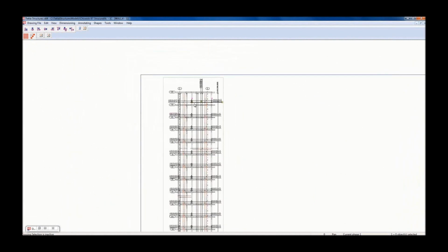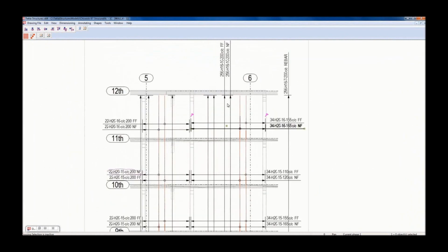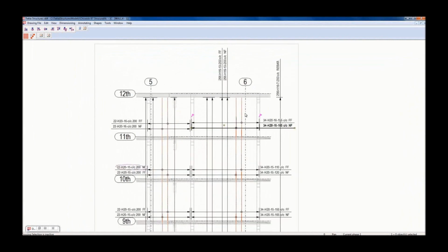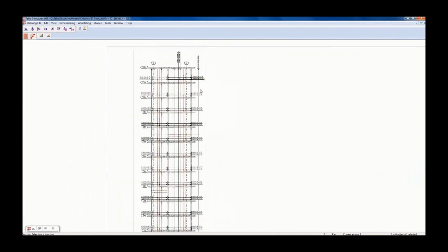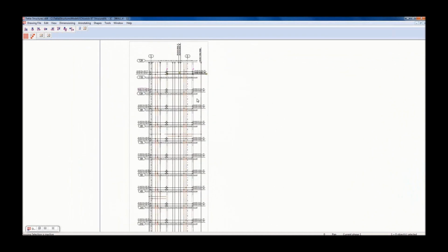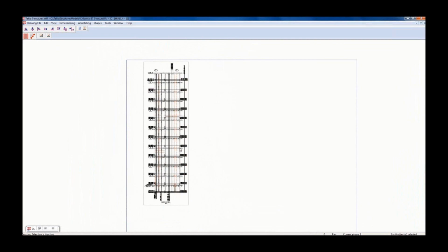So now, if you think when I made that assembly, those two back walls I made and all the panels I made into that what they call a cast unit. That's how it knows to quantify and only show bars that are in that cast unit on this element panel, and you just get this sheet.